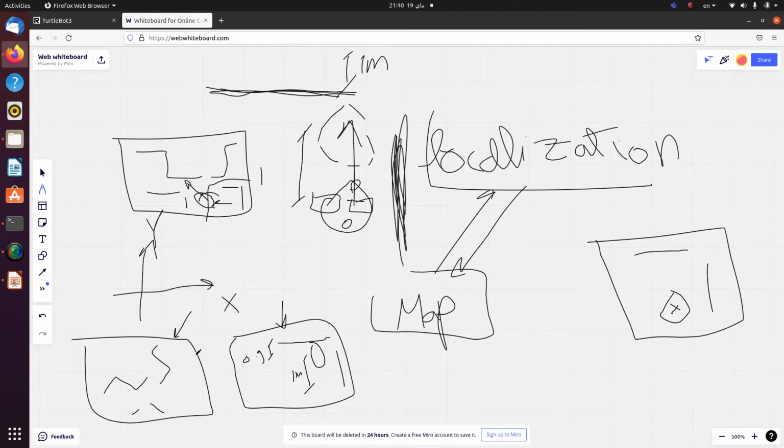So based on this localization data, I can reorient the new observation to map it to my global map. So I've got a local map, which is the local observation, and I got some global map that I keep building through individual observations. In the global map, the first observation was recorded right here. And according to this new observation and the localization data I got so far, I can deduce that this observation can be mapped to the global map to be somewhere here.